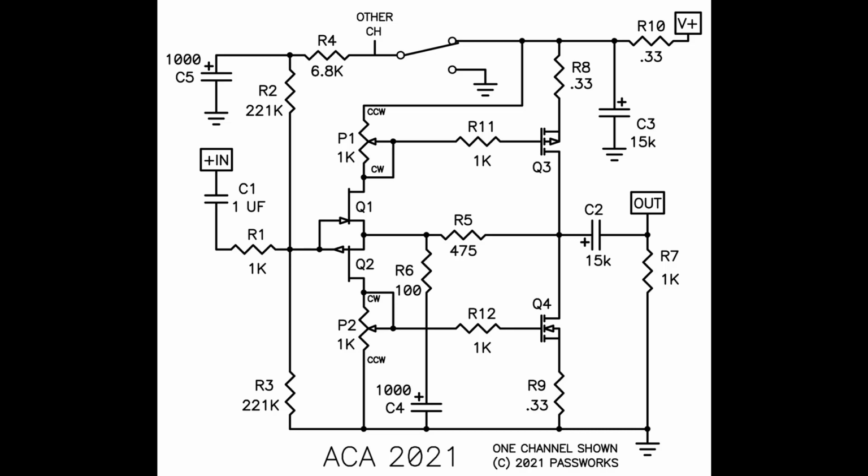You will see the power switch which puts the amplifier in a standby mode where the bias current is shut down so as to not waste power. Finally, we see the values for the feedback resistors whose ratio sets the output gain of the amplifier at 14 dB.